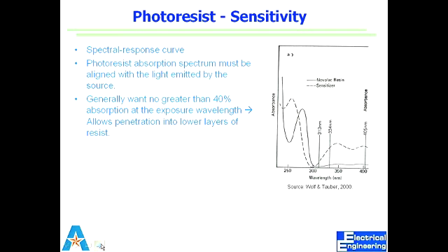So, as a designer, I have to see this plot of absorbance for that resist, and I have to then decide what optical system I need, what wavelength do I need to do my lithography. Right? If I use a 300 nanometer system or maybe 310 nanometer, will I get my exposure? Will I get my exposure? Guys, look at the plot.